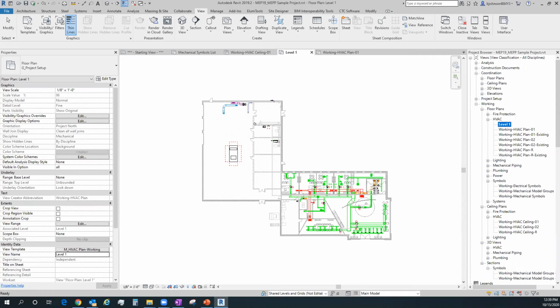So other typical reasons for crashes, excessive warnings. Again, if you have over 1,000, I would start working on them. If nobody in the group has time that's familiar with the project, then I would continue to watch. If it hits 2,000, then I'd make sure the project manager knows this needs to be done. If you hit 3,000, it needs to be done. Like, put somebody on it now.